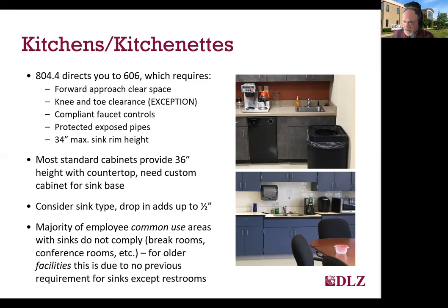or even higher, since the standard height of most base cabinets with a countertop is going to establish a 36-inch countertop. And if you use a drop-in sink, that might even add to that. So you can see on the bottom picture on this slide, they actually use a customized model for the base cabinet for the sink, and that sink is actually at 34 inches and does comply.